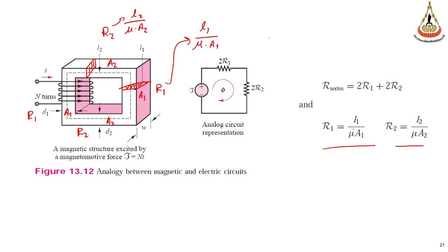And then we can calculate the reluctance, and we can calculate how much the flux is. F will be flux into total R, where total R is R series. We know R and we know F, so we know how much the flux is now. I think we can continue, no breaks. You don't need a break, right? Okay.